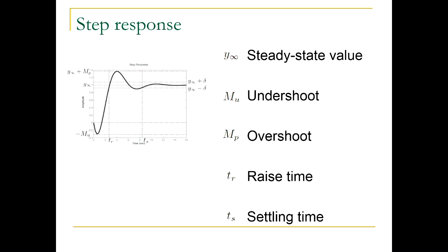Now, rise time is defined differently in different textbooks. By the way, different textbooks may use slightly different definitions of these features, and the mathematics behind them might be slightly different. So always check what definition they use, because that would determine what sort of mathematics you end up with. So what is the rise time? Often, it's denoted as the time needed to go from 10% of the steady state value to 90% of the steady state value. So rise time is in a way measuring the speed at which our system would respond.